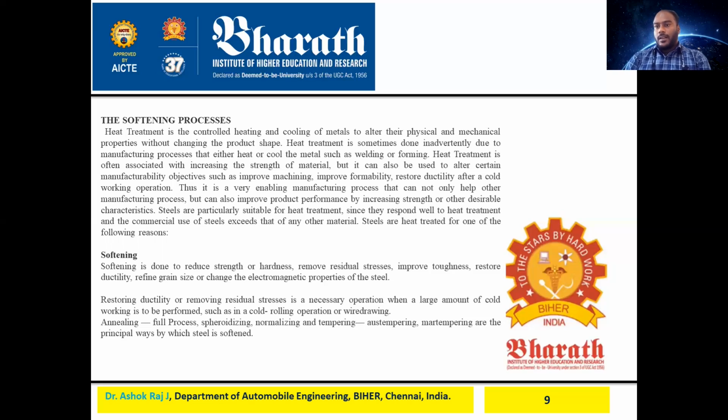Hardening, tensile strength and toughness, and maybe ductility of the material. And steels are particularly suitable for heat treatment since they respond well to it, and the commercial use of steel exceeds that of any other material. Steels are heat treated for one of the following reasons. What are the reasons? If you compare with other materials like titanium, aluminum, or copper, in most cases only steel alloys generally get heat treatment.